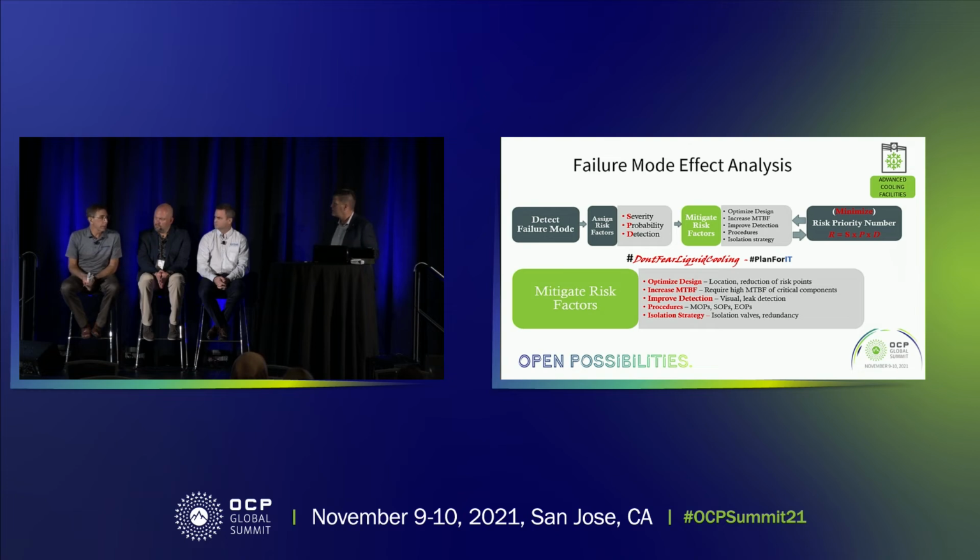Let me give you a real life example of that. Intel was big on FMEA, and they're pretty smart people who work there. So we had a data center that had overhead cooling, and we were running 16,400 GPM through that room, and it was all overhead, vertical and overhead, when it was all said and done. We went round and round about leak detection, put diapers on, put sensors on, put indicators on, and when we finally came down to it and thought about it correctly, we said the highest risk was one server rack, and this particular facility happened to have thousands, so one server rack. And the other thing was that most of those leaks are going to be leaks, not catastrophic failures, so they're going to be sprays or something else.